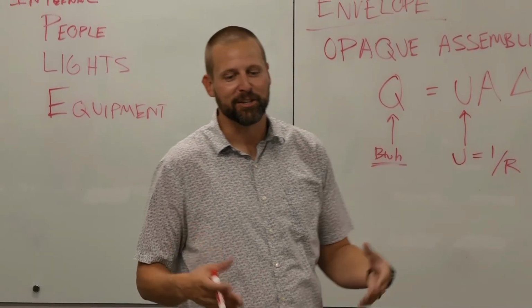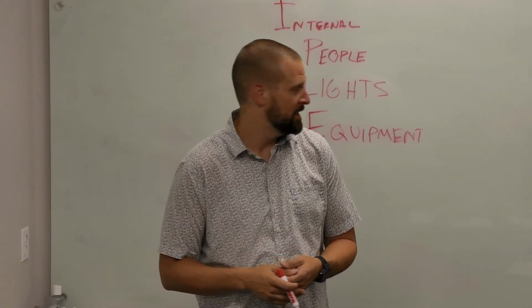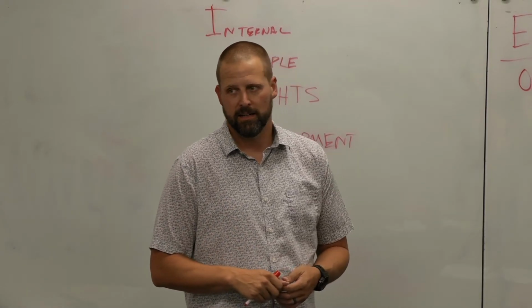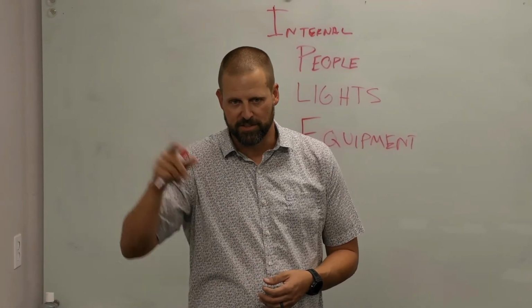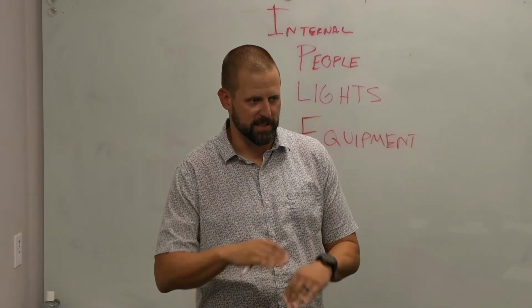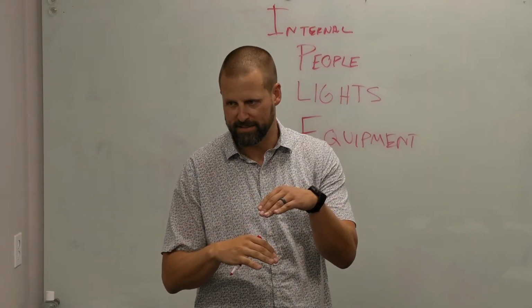But the U factor and R factors are how you tell how much something insulates. So if it's got a high R value, think good insulation. R13 is usually between the walls. When we talk roofs, we're usually talking a built up R30 roof or a batt R19 below.